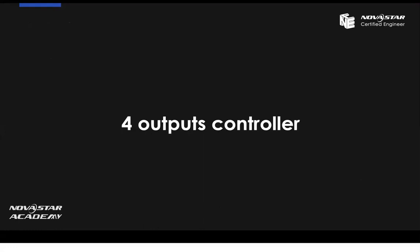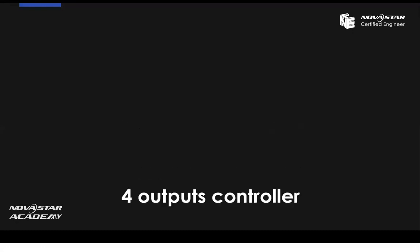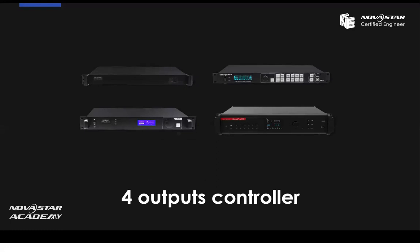Now we know that for each output port, the loading capacity is 650,000 pixels. So what about the 4-output-port controllers? If one output is 650,000, then 4 outputs should be 2.6 million pixels, because it's just multiplying by 4, right? But that result is wrong. The loading capacity for a 4-output controller is not 2.6 million pixels. It's 2.3 million pixels, which is the real capacity of these products.